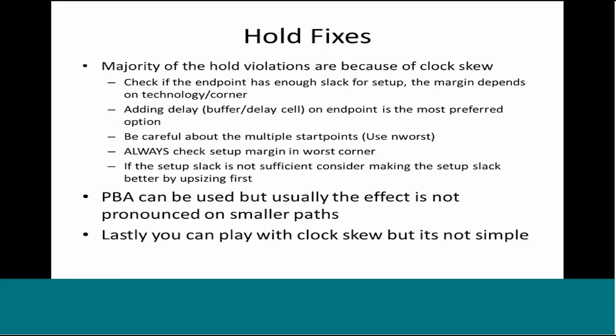But when you go to the backend, to the post-layout database, the number of hold violations will increase by a lot. For parts like shift registers and all the scan paths, for example, all such paths have virtually no combinational logic between register to register. Because of the clock skew, because of the difference in the arrival timing, the clock latencies of the two clocks, the hold violations will occur.